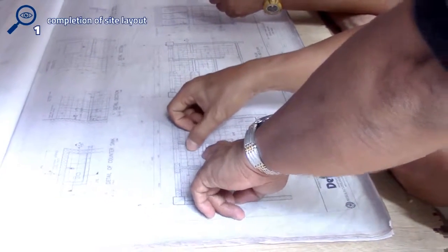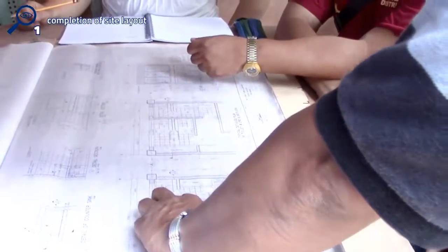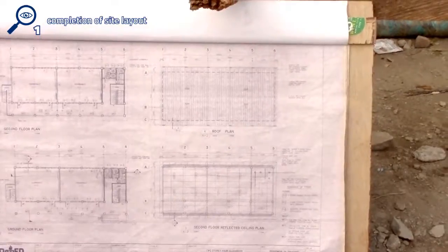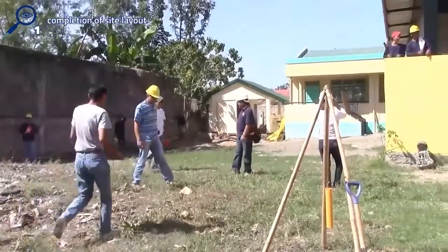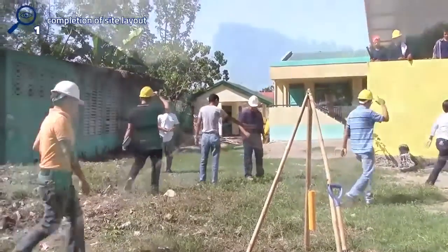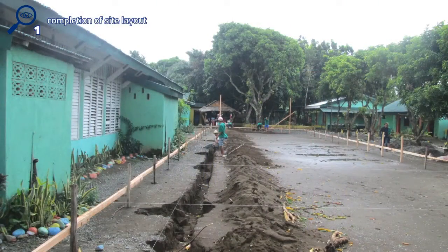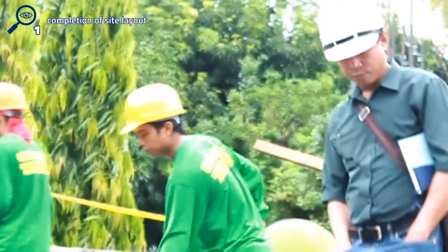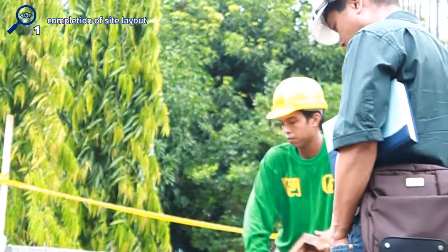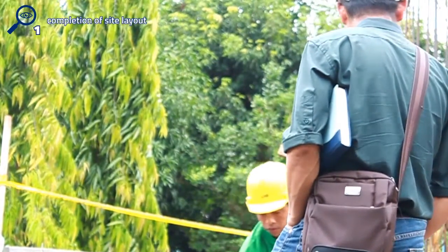Key inspection point 1. The engineer must verify that the actual site layout is as per the approved site development plan. The contractor should set out the actual site for the building works. This should be done by physically fixing batter boards to their horizontal position to establish the actual position on the ground where the classrooms will be constructed. Once this work has been completed, the engineer should carry out key inspection point 1.